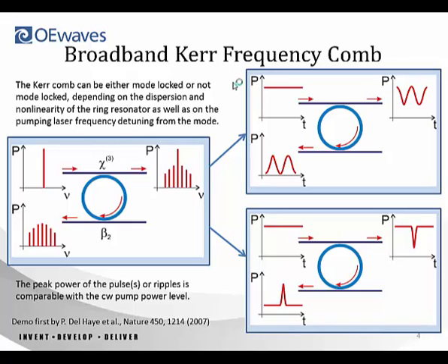As I mentioned in the presentations, we are interested in generation of radio frequency signals produced by this frequency comb on fast photodiodes. This corresponds to what Kerry discussed with brilliant lasers. With this perspective, we don't care much if we have a pulse in the system or not. We're interested in the spectral purity of the RF signal. And as you will see, it is not necessary to have a short pulse there. It is possible to just phase lock a number of modes that don't correspond to a soliton traveling within the cavity.